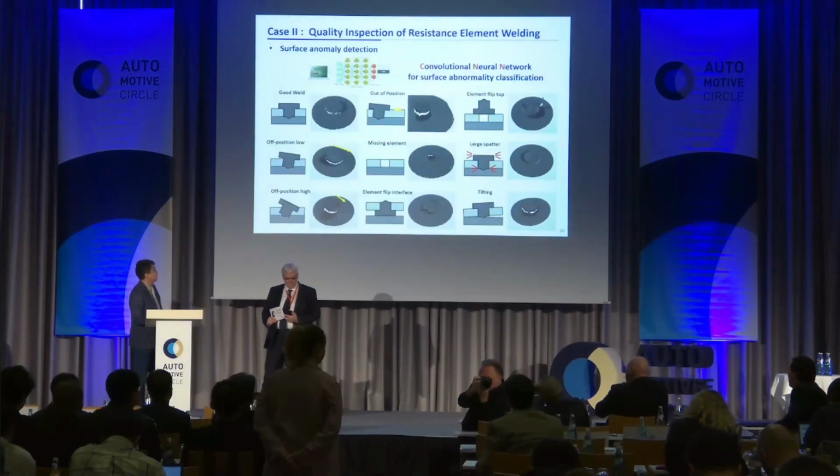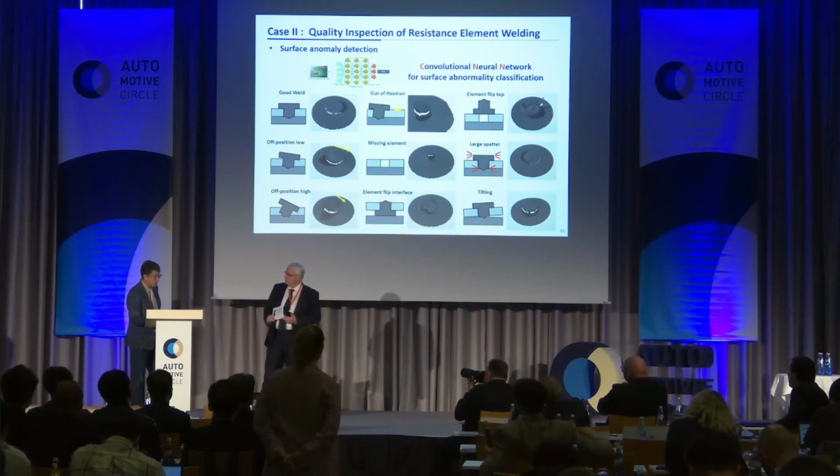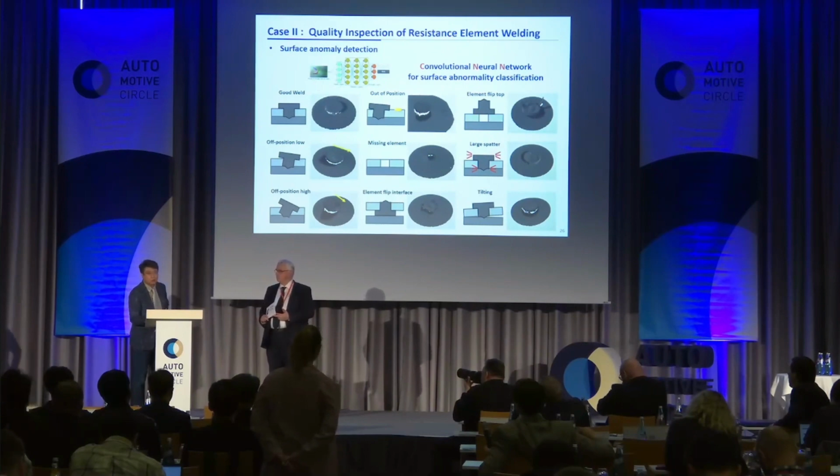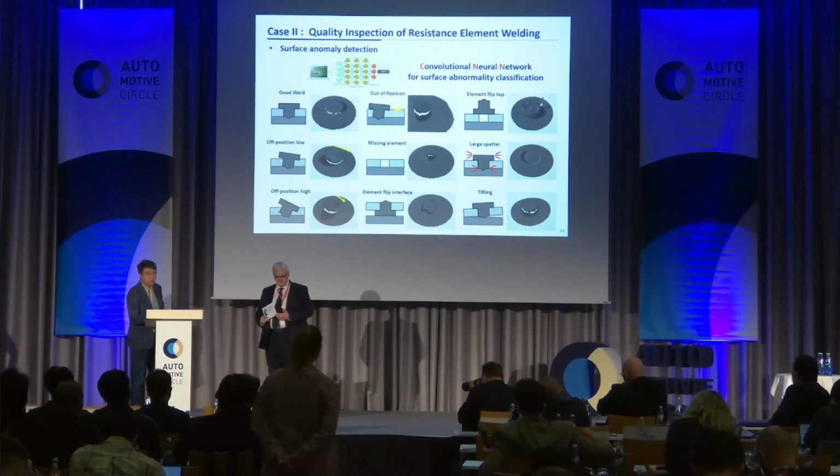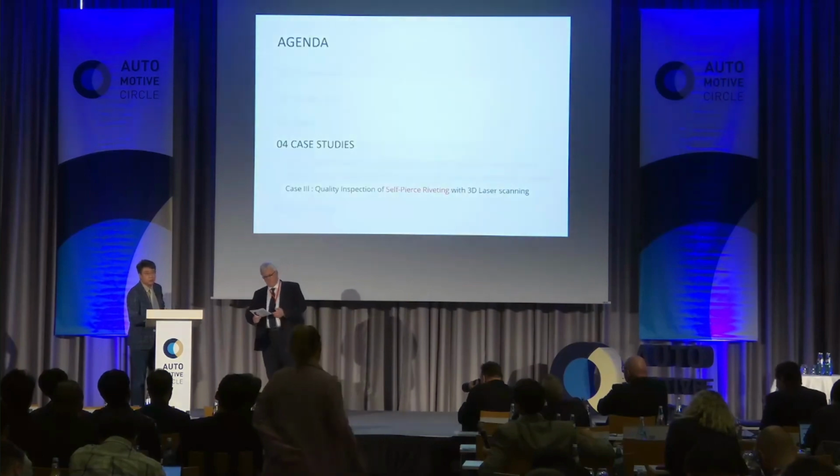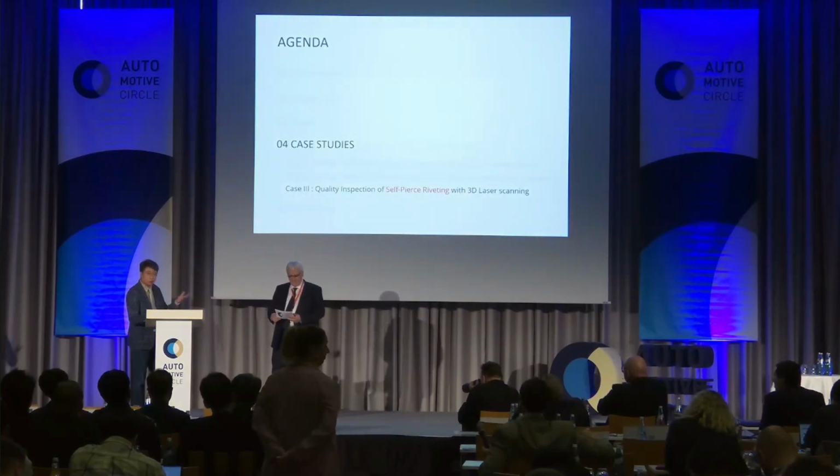Yes, that was also a very good point. We actually experienced that a worn electrode gives different indentation geometries. So in the same way, we implemented a logical algorithm to compensate for those changes with electrode degradation.